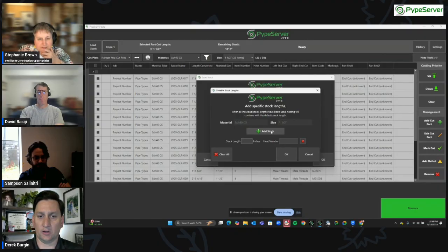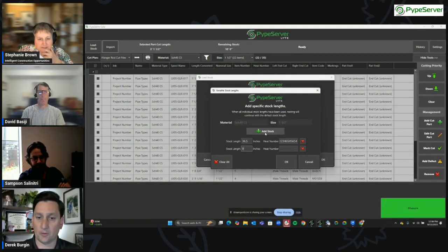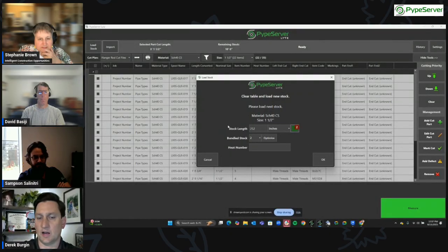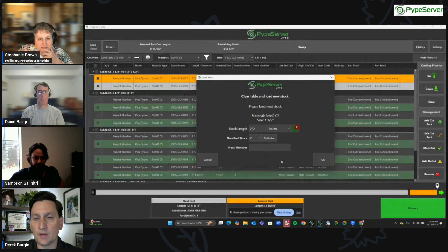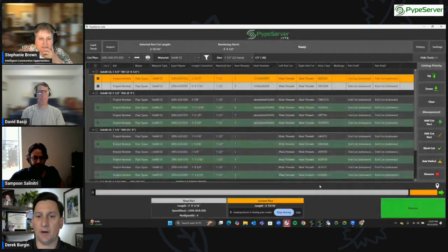And what we have the ability to do is say, hey, we have a piece that's 36.5 inches. And if you're doing heat number tracking, we can go ahead and throw that number in right there. Then we could say, hey, we have another piece that's 96 inches and it has this heat number to it. And then after that, it's going to go to the stock, our standard stock length of 252. We hit OK. And what the system is going to do is utilize a nesting algorithm to basically pack in that first stick of pipe with as many cuts as it possibly can.